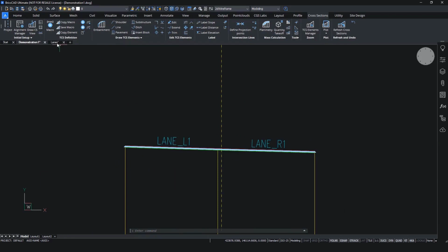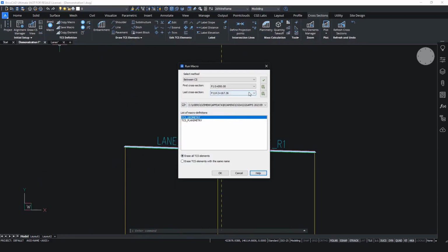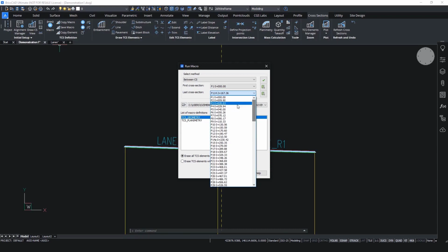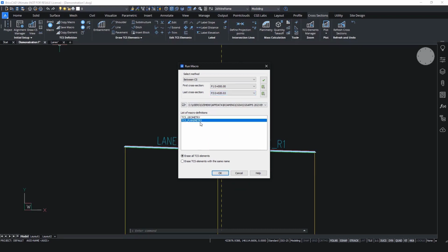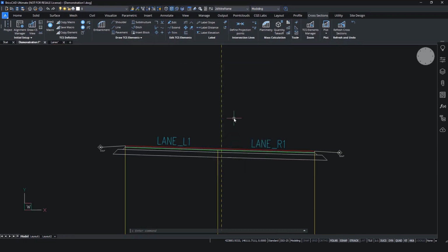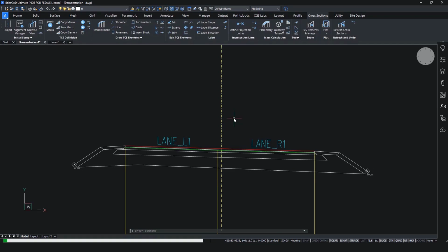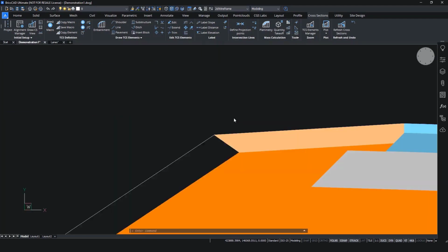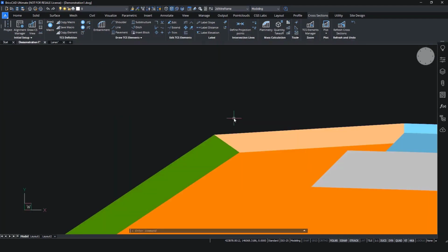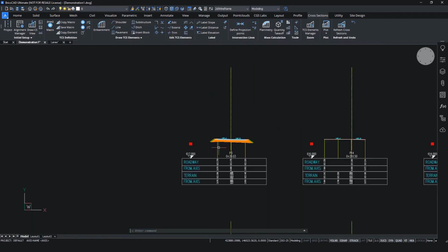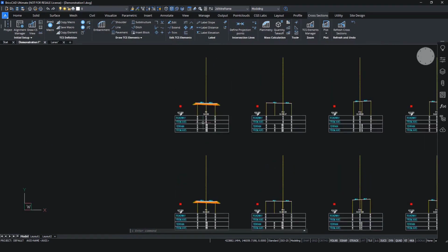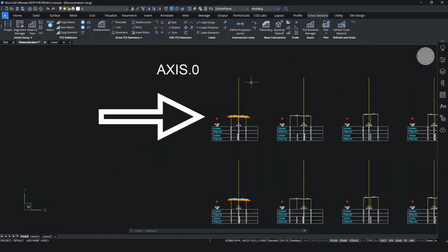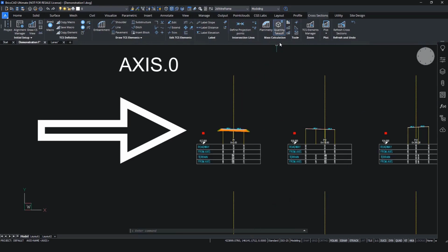For this case, we can also use macro, so I will use that on the first 3 cross sections, and I will draw it again. In this macro, I already defined all the materials and the elements that I want to have. So I want to draw it by hand. So here are the first 3 cross sections, and I can make a quantity takeoff.